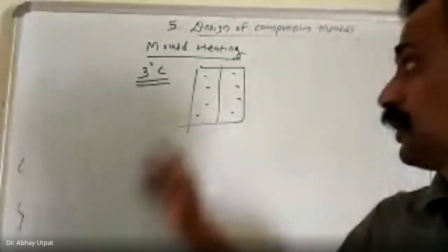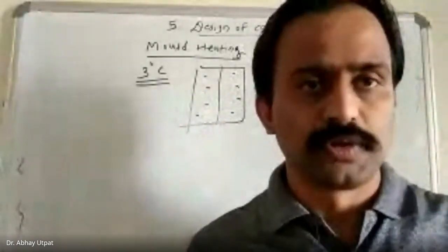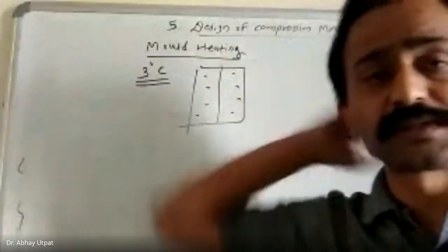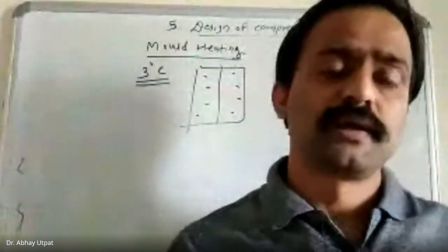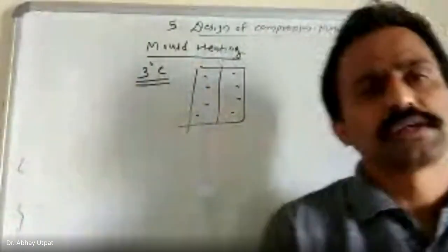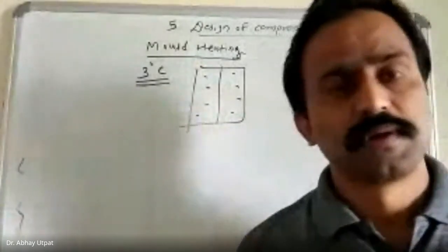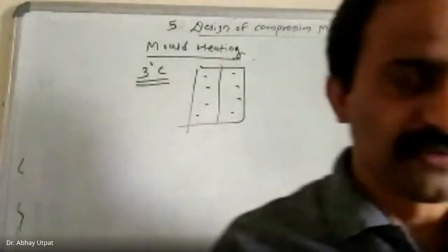So just I will say tolerance of 3 degrees Celsius. If it is there, we can say that our condition is good. So if you find more difference between this point temperature and this point temperature, then you can say that some optimum temperature is to be maintained, because uneven heating of the mold will cause deteriorating the properties of the product which are produced by using that mold. So mold heating is an important step here. Difference of 3 degrees you have written.